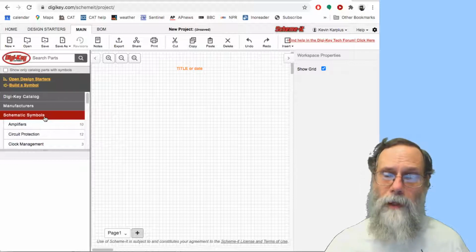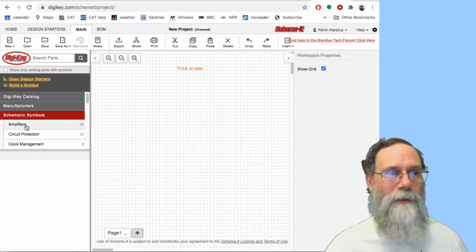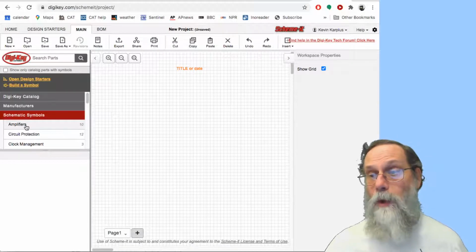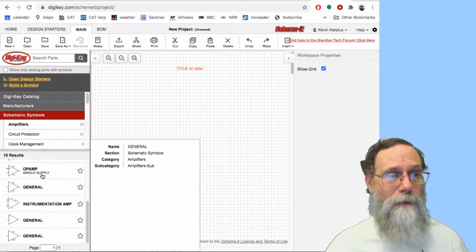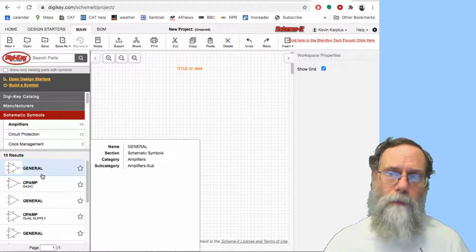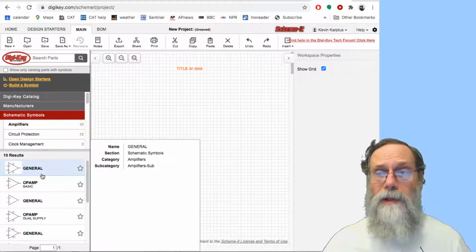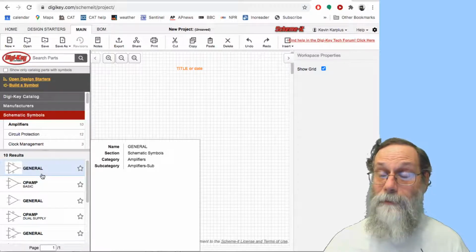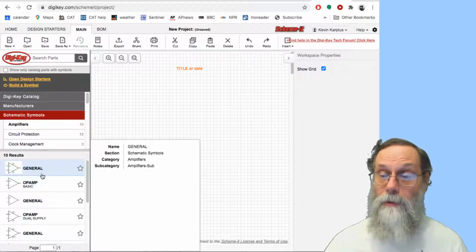And the diagram that I was trying to draw, that backdrop I've been using, had an amplifier and a bunch of ports and a couple of resistors. So let's start with the amplifier. There's a bunch of different amplifiers here, and they all look kind of the same. Which one do we pick? Well, advice that I gave in an earlier video was that because there's a tendency for students to forget to connect up power and ground to their amplifiers, it's a good idea for your schematic diagram to remind you.